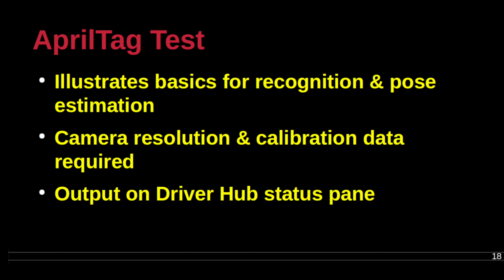It is instructive to use the camera stream to view the scene prior to touching the play button on the driver hub. It is also helpful to assess the field environment for consistent detection of the April tags by moving the April tags slightly and then refreshing the camera view by tapping on the display on the driver hub. Once the play button is pressed, the camera stream will not be available for the remainder of the run.